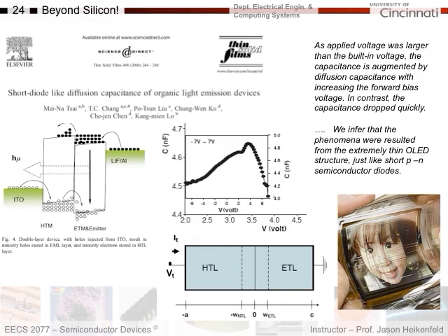It's interesting that in this course we talk about silicon, but these sorts of capacitances show up in any type of diode device. It turns out that OLED displays, organic light-emitting diode displays, which are some of the new displays you're seeing come out in smartphones, are made out of diodes, right? And so here's a paper. I was looking at some papers and found one where they were talking about storage capacitance in a diode. They measured the capacitance versus voltage, and they found that when they reverse biased it, the capacitance went down because you're looking at depletion capacitance and the depletion region is increasing.